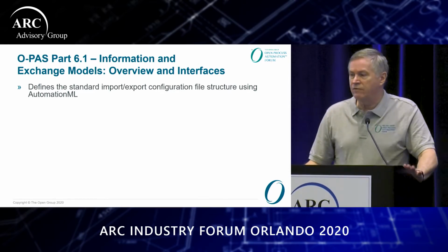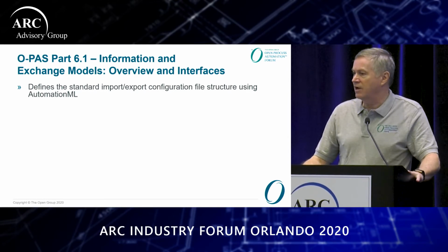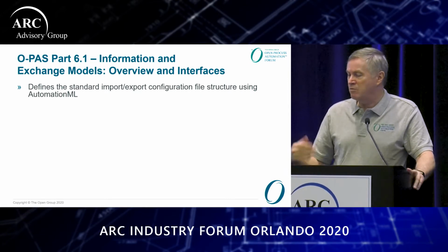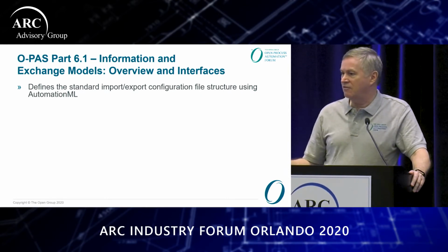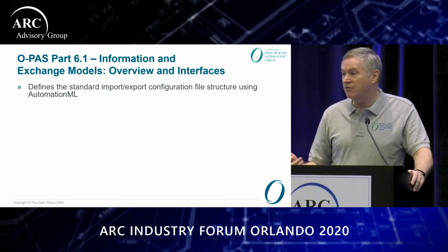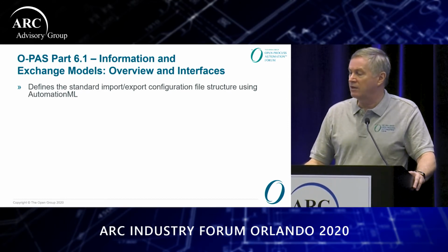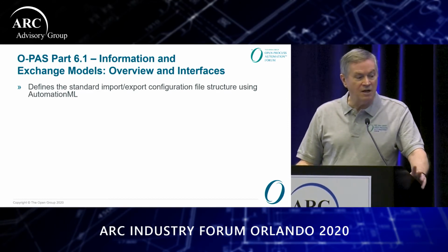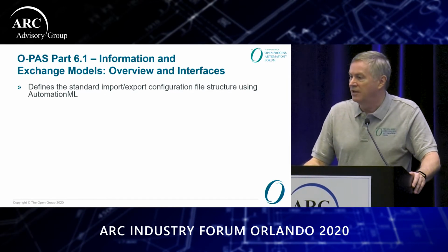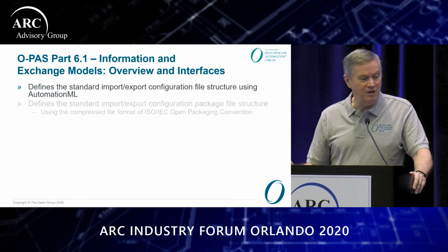The whole purpose of version 2 was portable configurations. So to have portable configurations, we've got to have a standard format that any certified vendor will be able to import, make whatever changes they have, define their tags, define their programs, their function blocks, define any of the other information, alarm information, et cetera, and be able to export it back out in a format that others would understand. So it's a standard import-export configuration file format. It's based on AutomationML. If any of you are familiar with MTP, you're going to see a lot of familiarity here of what we're doing.